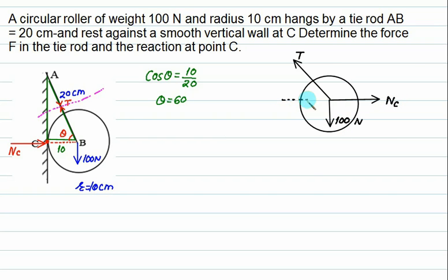The angle made by tension is theta. And what is the value of theta? Theta equals 60. Is it correct, everybody? Now the same FBD I will use for Lami's theorem because I have three forces only.